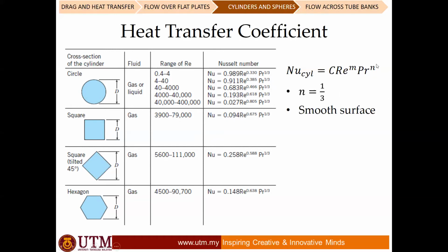So in general, this is the equation. The C value is determined by experiment. We don't do the experiment; they did the experiment before and then made a correlation. So if, let's say, your solid is a square, your Reynolds number is in this region, and you use this Nusselt number correlation. This will be given as well in the final exam, in a table. So you need to make sure you choose the correlation based on your physics and the geometry of your problem.